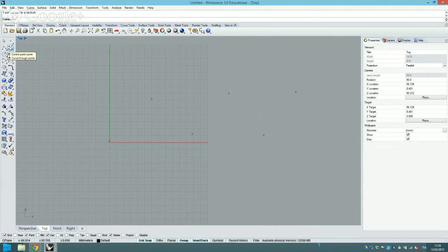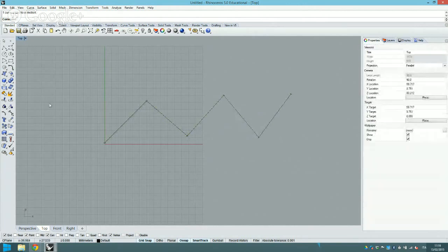So if you left-click on this curve command here, on the command line is written start of curve, and degree is set to 3. If I press on the degree, I can change it, for example, to 1 and press enter. So now by snapping to these points, make sure that you have your point O-snap activated, I can draw a line with degree 1, which means it is a polyline.